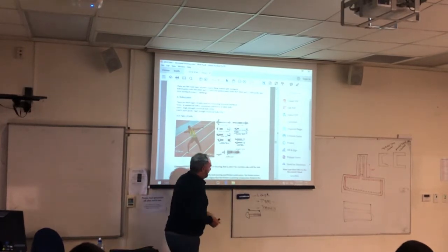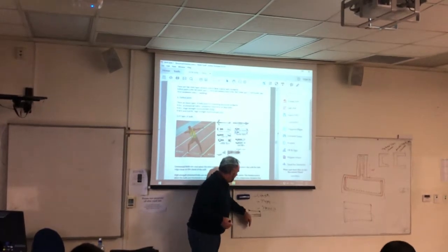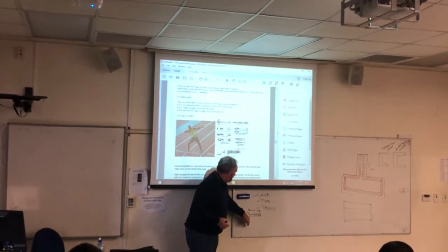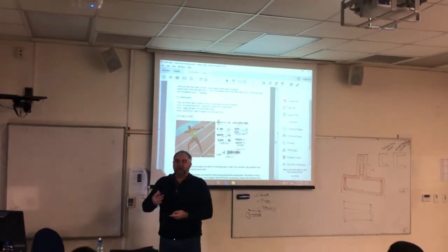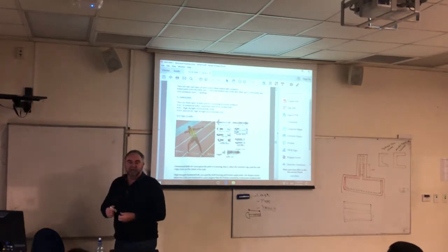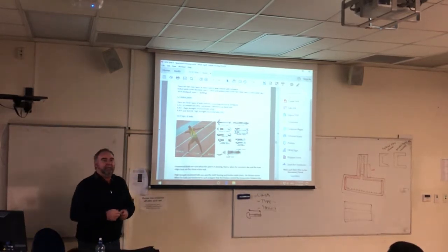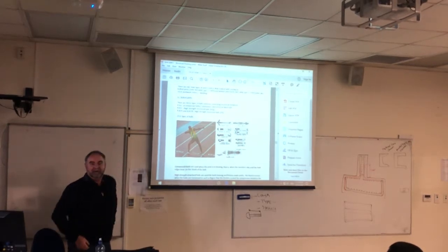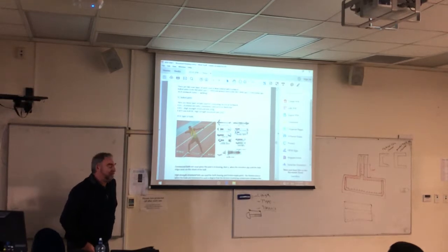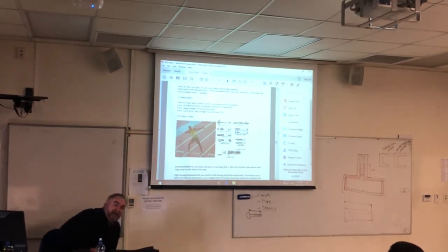When we talk about length, it's from where it goes through at that point right through to the very end. So if you've got a washer and a nut, you've got to have at least a wee bit of room at the end to tighten that up. And also there are situations where you don't want too much length because it'll be sticking out, and it may cause an issue if it sticks out too far as well.